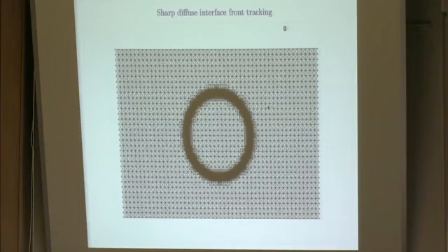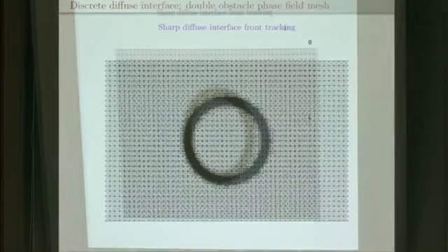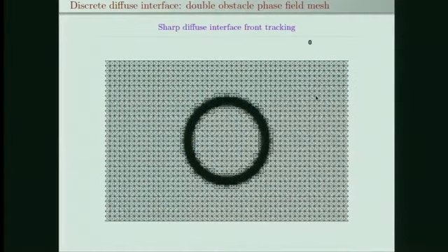So when you're using a phase field, of course, you could have used this grid, this mesh here, and refined it everywhere. But that's kind of crazy, because you need a fine mesh because you're using a phase field, but you don't need a fine mesh to solve the Navier-Stokes equations, possibly. Okay, so your game is you want to use an underlying fixed grid.